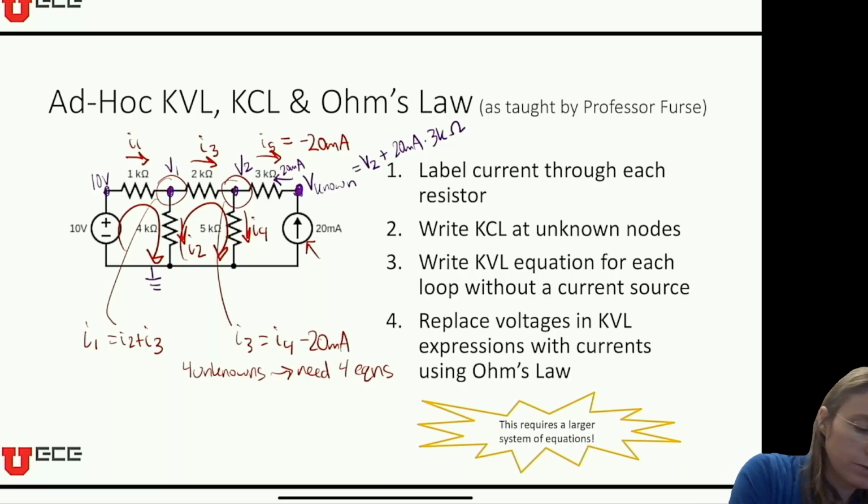So in the case of this left one, if I start here, I'll look at the sign where I come out. I get 10 volts minus whatever the voltage is across V1 minus whatever the voltage is, right? Because this is V1. Over here in this direction of the arrow is V2.